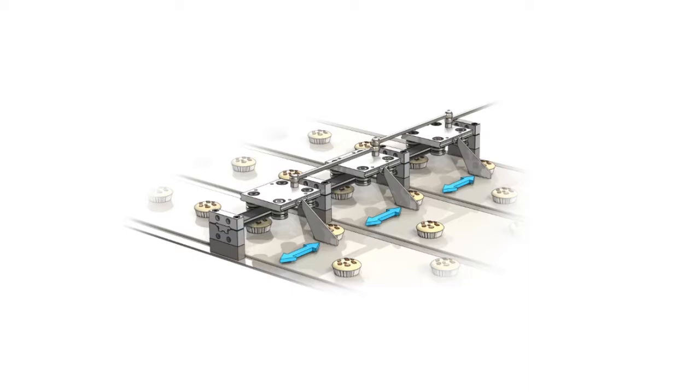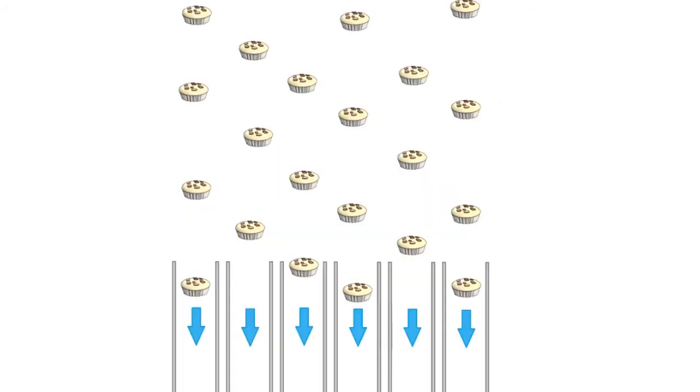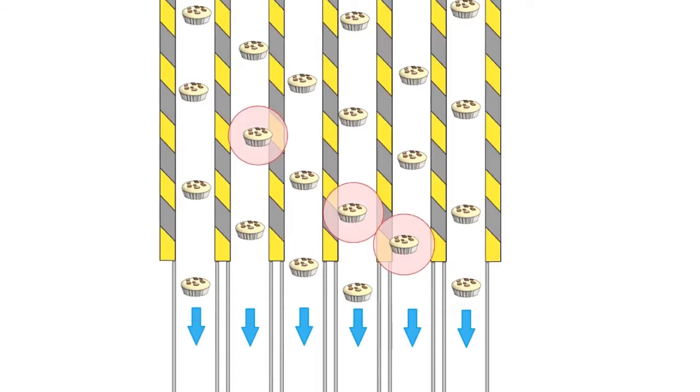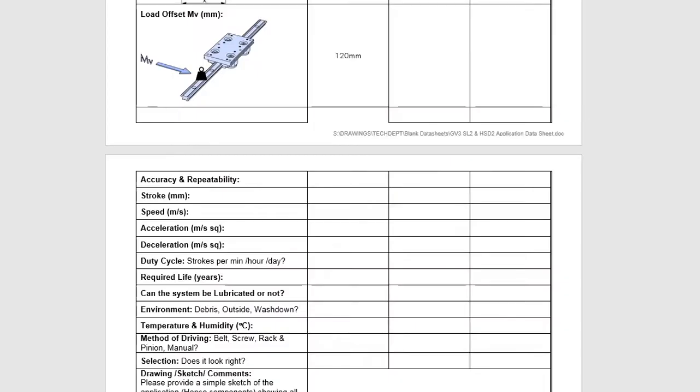lined up for packaging. Each cake is 50 mm wide, and the channel they fit into in the next process is 60 mm wide. The customer needs the centre of each cake to be within 5 mm of the centre line of the channel, so that they don't clash with the channel as they go through. These cakes won't make it through, as they are outside the line of the channel. The repeatability required is therefore plus or minus 5 mm.